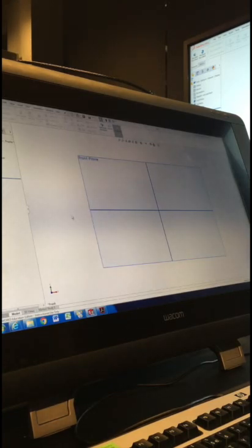The origin, which you can see here in the feature tree, if you select that, the origin is a point that is at the middle of those three planes. So that is essentially your 0, 0, 0 location. That's important. The origin is really important because that helps us have a reference point for whatever geometry we're building. Whenever we build a feature of a part, we always start with geometry, and what I always want you to think about is how am I referencing that to the origin?